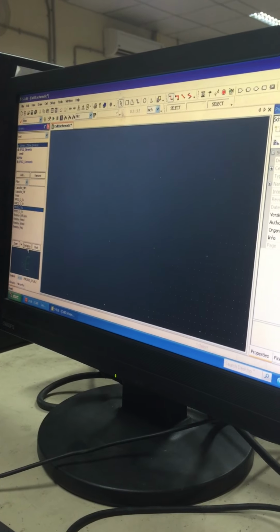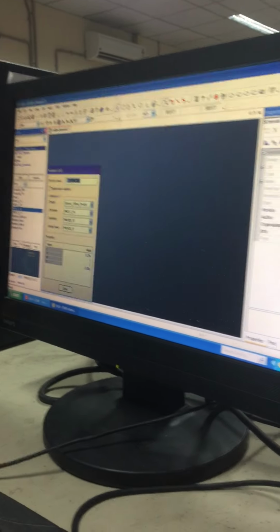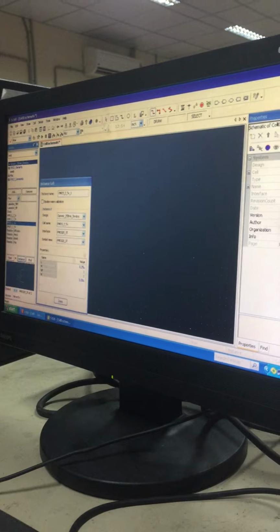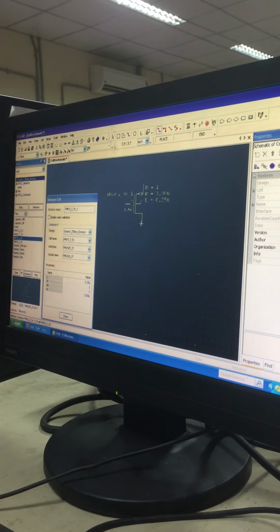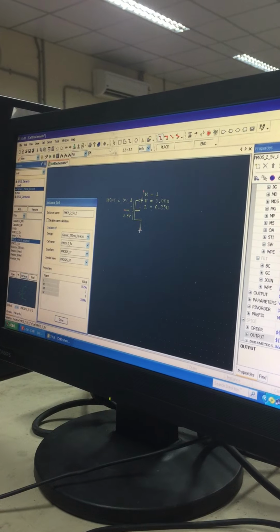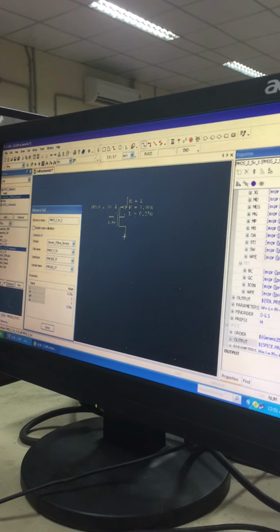Yes. When you single click on the component, you have a window here. In that you have an option called instance. Click on it, and then simply drag your mouse. You can see the component here. You can place it anywhere and click it, you have to left click. The scroll button has to be used only for zoom in and zoom out.